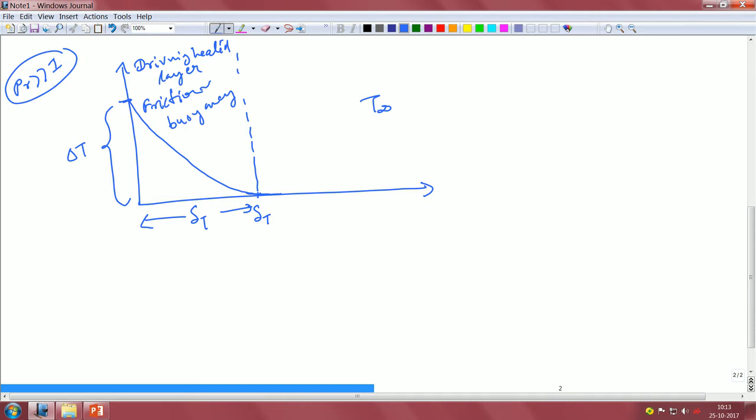Okay. Now, what about the velocity? The natural question is that we have a situation in which the temperature decays and is gone, but what about the velocity now? How would the velocity boundary layer behave, because remember it is a Prandtl number much greater than 1 situation? So, what happens in the region to the right of this delta T? Of course, the temperature does not exist anymore.